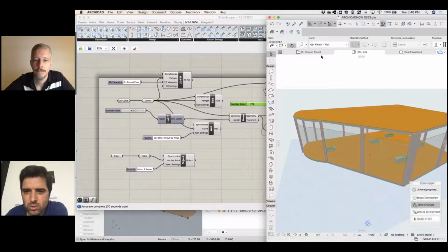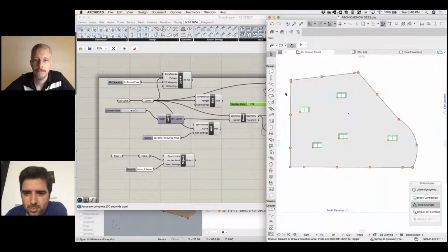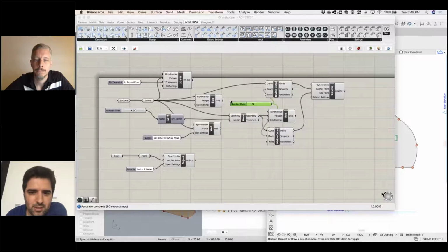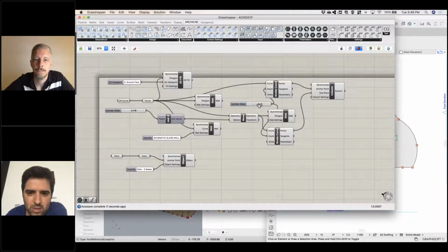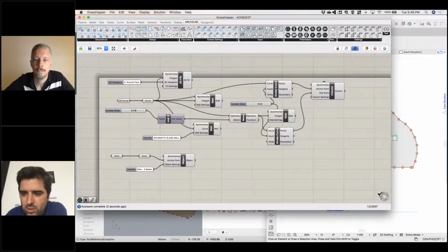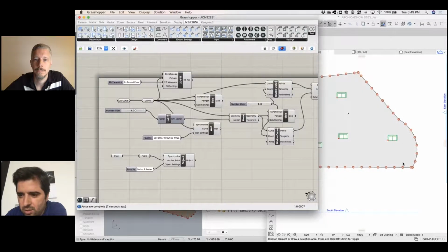So what this will do is it will place a column on every corner every time that there is an inflection point, but it's still dividing the distance so that we have always the same distance in between the 12 numbers of columns. So if I move now, I want 48. What it's basically doing is dividing the whole curve into 48 columns.